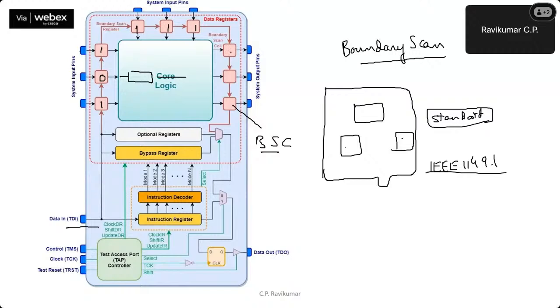Okay, so maybe the good response happens to be 1 1 0, and a faulty circuit response could be something different. Now, having captured the values into these cells, we can again go and shift out the contents of these cells, and go to what is called the test data output.